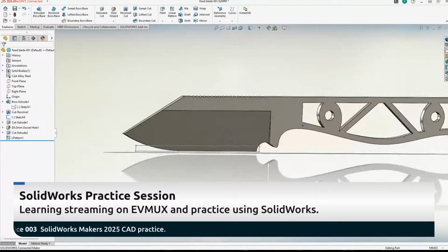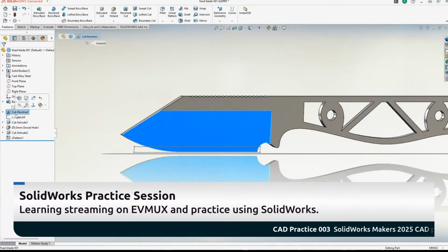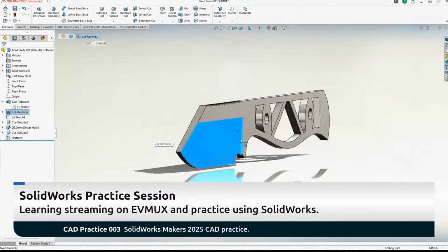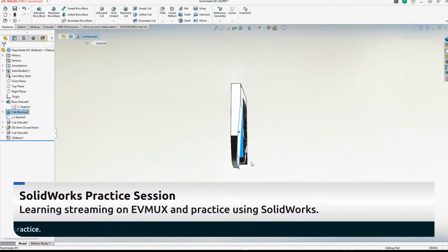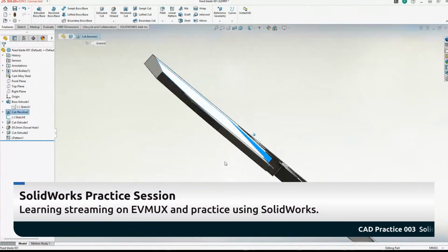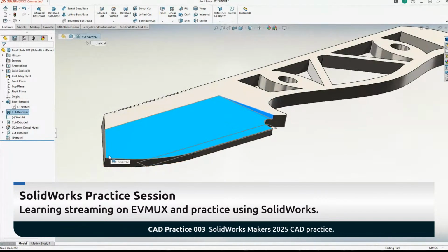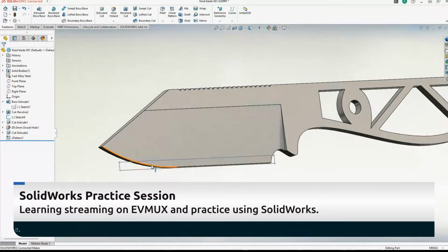So this cut revolve. Since this is flat, but this curves up, when you cut this way, it's wider here than it is down here. That's the problem. So that's why I can't do it this way, because then if I put the final bevel on here, it gets wider here, and I want it to be consistent the whole way. So I found what I was doing wrong is the way that I constructed this sketch.